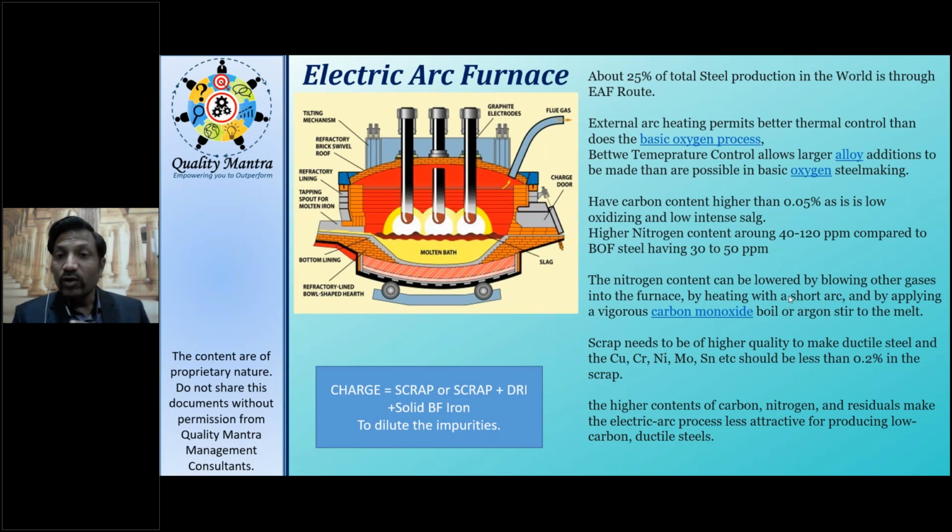And nitrogen, what will it cause? We have studied this yesterday, we discussed why you are not using air but oxygen. Sir, nitrogen from air? Cracks can form. Yeah, what do we call that? Nitrogen embrittlement. Yes. So in the first place, earlier people were using air, but they shifted to the oxygen process, because oxygen gives the advantage of lower nitrogen ppm.